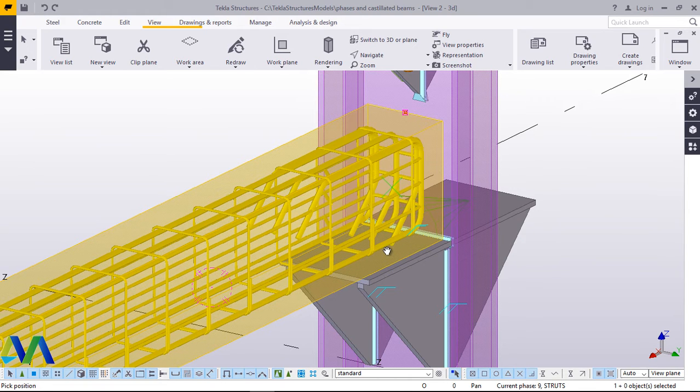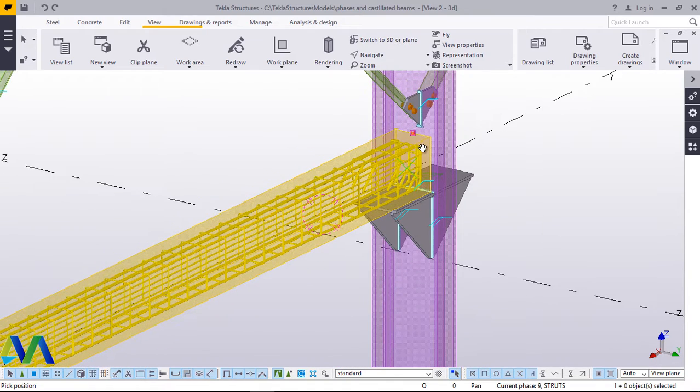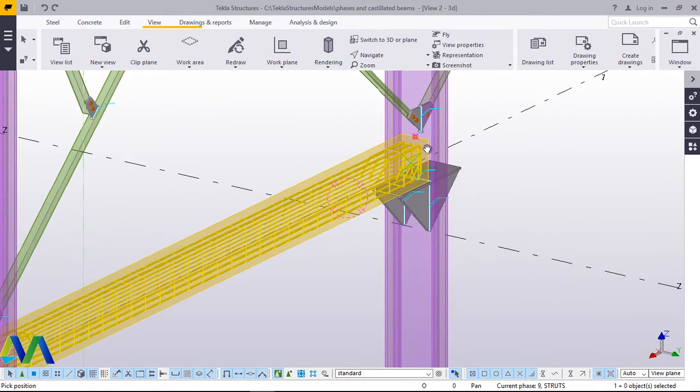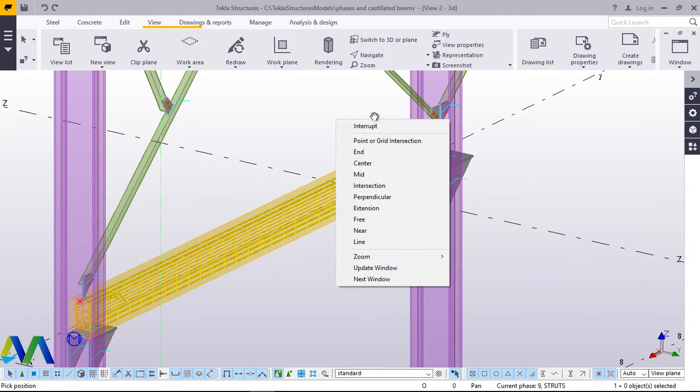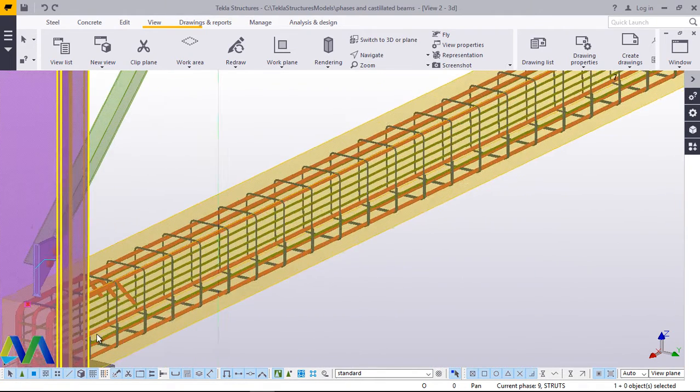You weld the bottom rebars to that plate, and at the very end you weld some anchors to reinforce the rebars here prior to doing your formwork and doing the general casting of the beams. Now, having done that, all these will be similar all round.